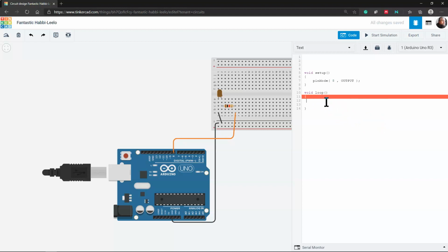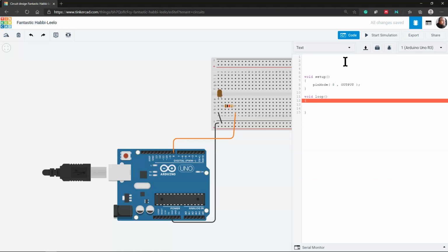Okay. Well, next for us, sometimes having hard-coded values can be a pain in the butt, and a lot of examples out there will do this. We can see that we've got this hard-coded 8, which is supposed to be the pin for the actual light, but this is not really descriptive. So right now, it'd be really good to go in and start defining some constants that you can use to represent what you're working with. This would be really good, especially later on as things get more complex for your projects, that you start naming your variables and the pin numbers and how they're being used to make your code easier to read. So one way to do that is const int